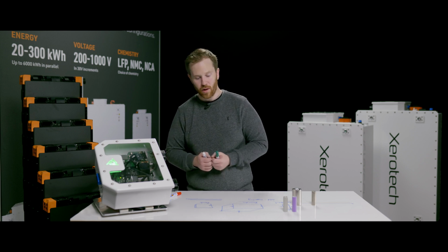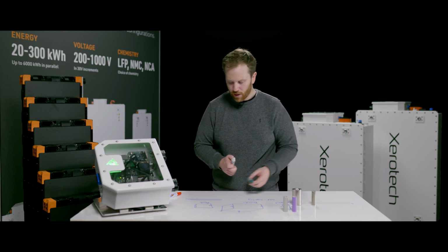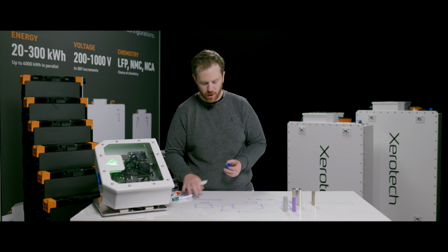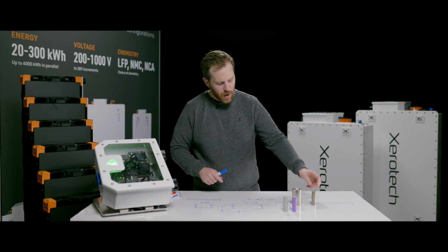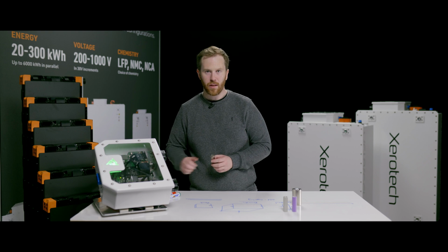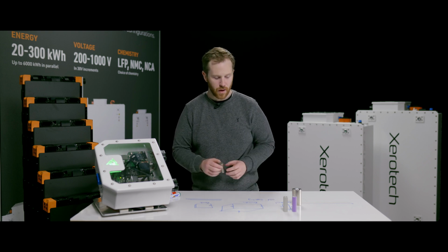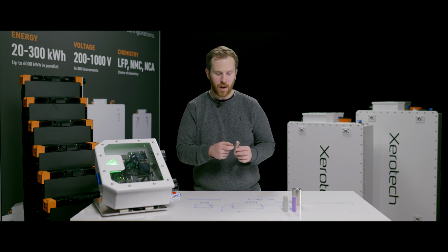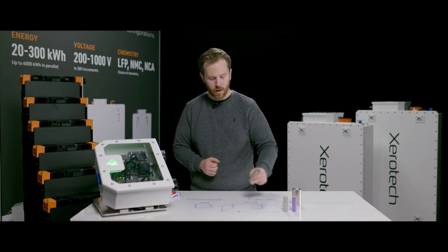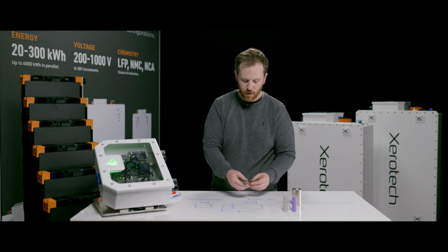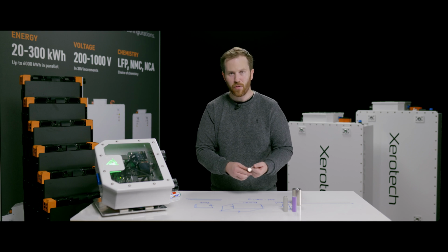So that's one consideration to look at. The other big one that's really important in all practical engineering is that safety does become an issue for battery cells, particularly high energy density. So it's really useful to have a metal can around your battery. It provides mechanical strength, it provides heat resistance, it provides thermal runaway protection, and it's a self-supporting structure.